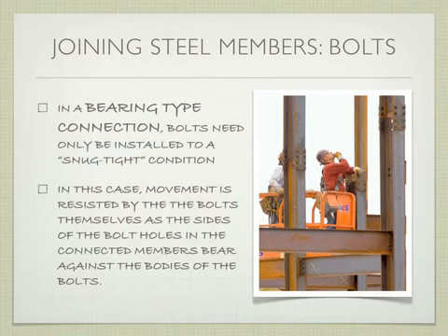So the idea here is that if I had a bolt, and I was bolting two pieces together, and I had a hole through one piece and a hole through another piece, in a bearing-type connection, the shear strength of this bolt not being able to split apart is what's holding this connection together. I'm not applying any kind of weird lateral forces to it. It's just straight down. I have weight resting on one piece, and I have another piece that's supporting that. The ability of them not to slide past one another is that bearing strength.